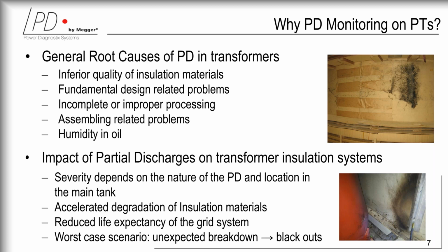The usual phenomenon, as you know, is that problems with the insulation, particularly with paper, generate certain gases, and these gases are effectively explosive gases, acetylene, methane, and so on, and those can cause significant issues. The impact of partial discharge on transformer insulation can have a different level of severity. In fact, during the acceptance testing, both factory and site, there are certain predefined limits for the partial discharge that can occur at different voltages for a certain amount of time, etc. All these are specified in IEC type norms, and that's how all transformer factories are testing their devices.